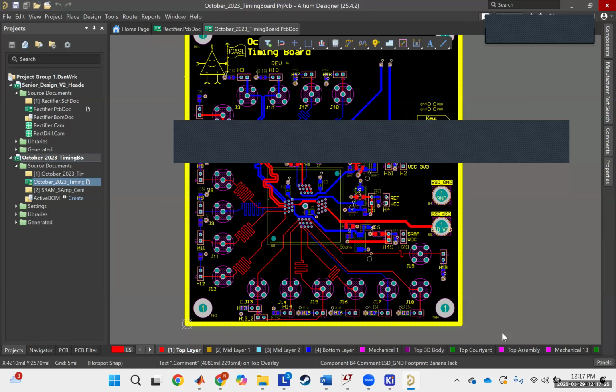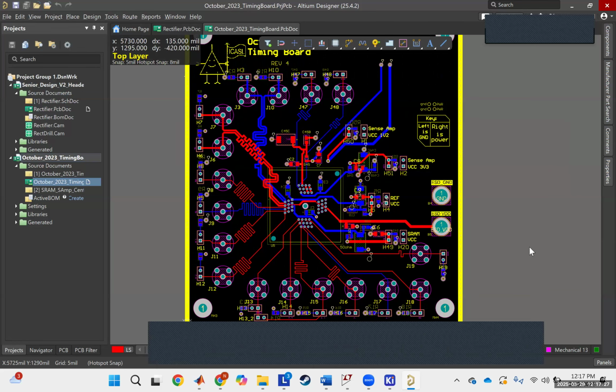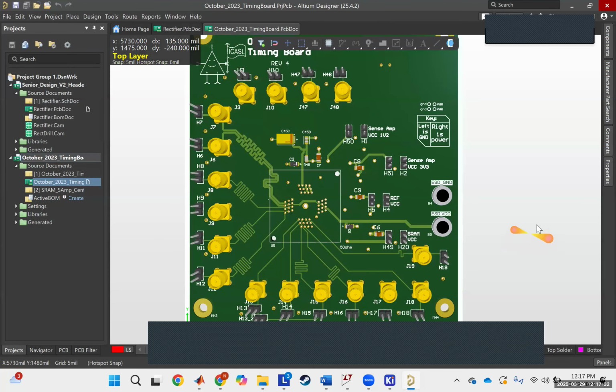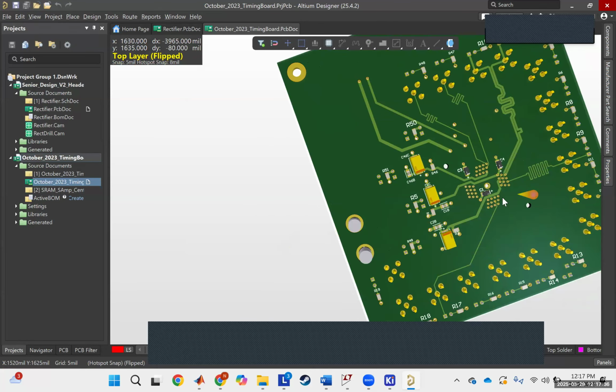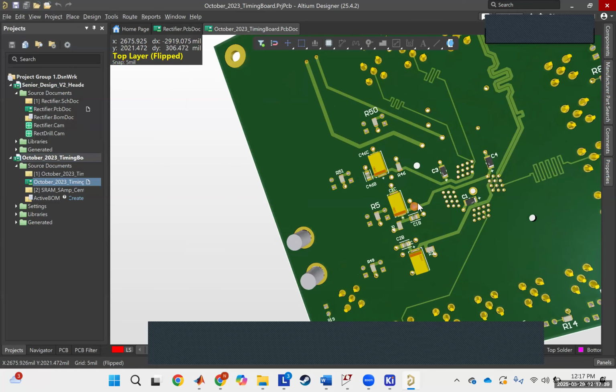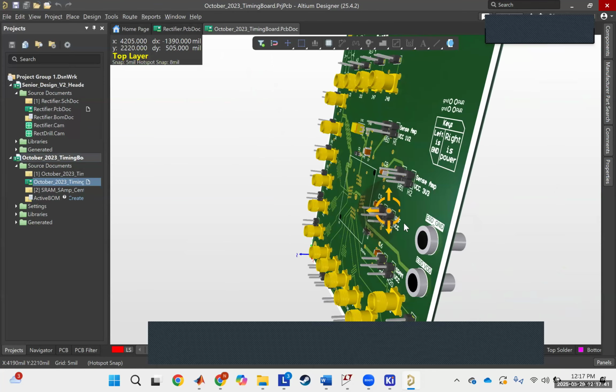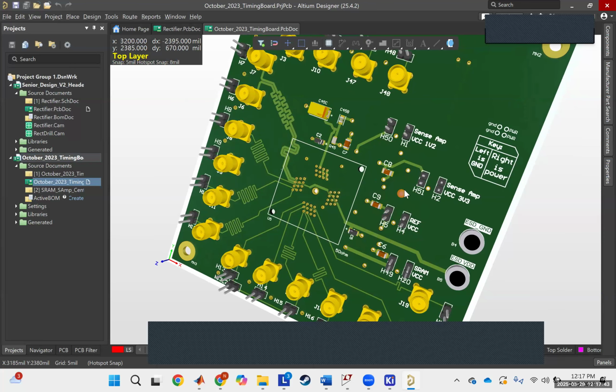So one other thing I wanted to show you: on our last board, we only looked at the top. We didn't put anything on the bottom. But you can always put components on the bottom of your board. If you look here, imagine we got a stencil for this board. You'd choose which side you want to use the stencil on, because you can't technically use the stencil on both sides. Imagine you put the stencil down, you put your components on, you heat gun it or put it in the solder oven.